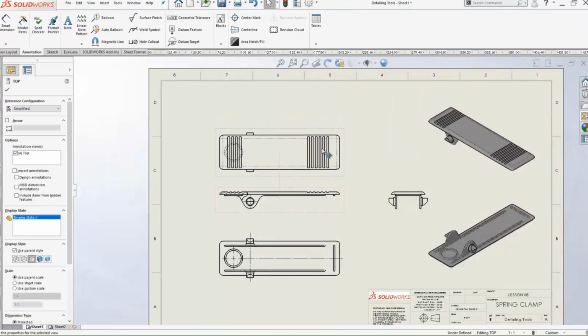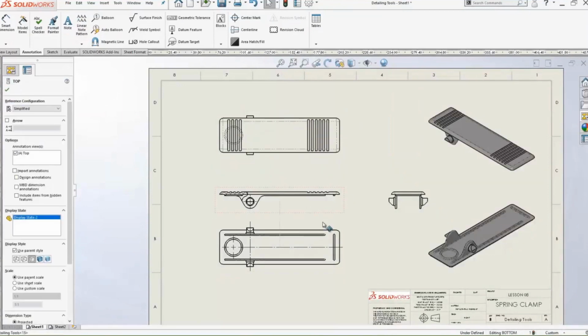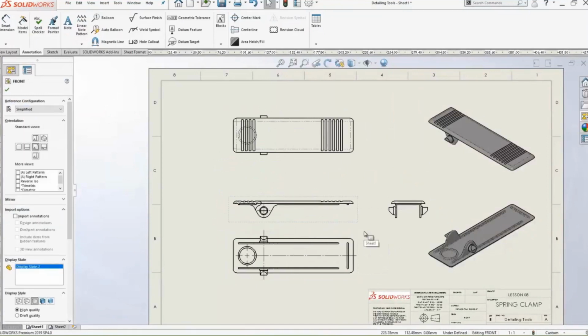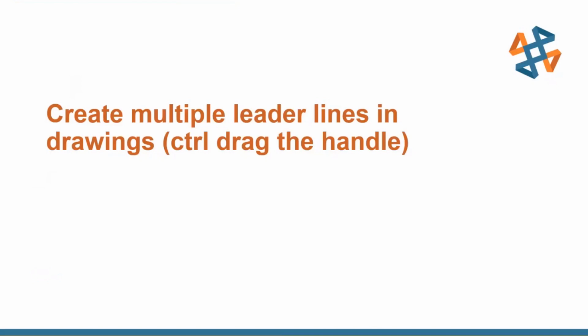Don't worry about that. Just hold down the Alt key. So if you hold down the Alt key, no matter where you select on the drawing view, you will simply move the drawing view. So much, much easier. I like to add that this also works for tables in your SOLIDWORKS drawings. So you don't need to select a table and choose the little microscopic cross symbol to move it. Just Alt, drag a table around, and it works the same way. So really subtle enhancement. I maybe shouldn't call it that, but that's how I think about it, that they've added to tables, drawing views, much, much easier way to navigate.